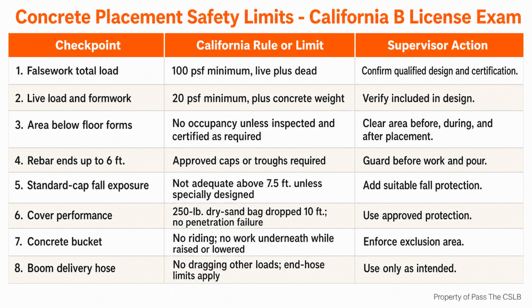Imagine a crew setting upper wall forms from an elevated platform while standard caps sit on the vertical bars below. The presence of caps does not end the analysis. I compare the possible fall distance with the cap limitation and require the appropriate fall protection before the work continues. That is supervision based on the actual exposure, not on the appearance of compliance. I also treat rebar protection as a pre-pour item, not something to fix after the pump arrives.